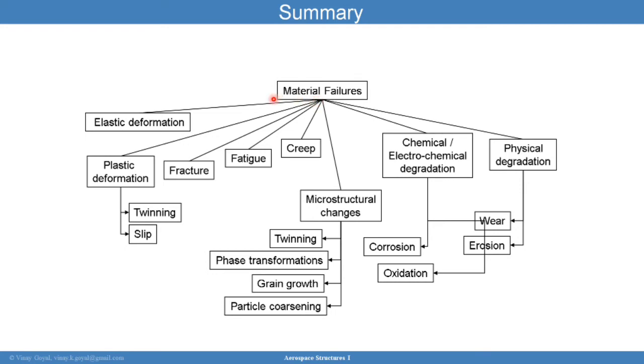You could have elastic deformation that for brittle material, that's all you need and you have failure, or the elastic deformation could be a problem from the functional performance standpoint, meaning the deformations could be too large for the system to operate properly, perhaps through an interference event.